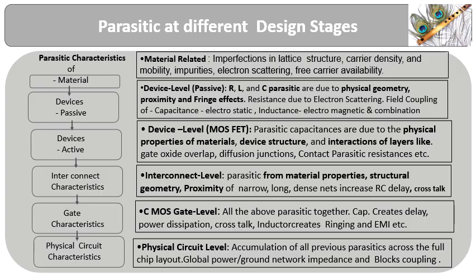At the gate level, these parasitics manifest as slower switching speeds and increased leakage currents, directly impacting power efficiency and speed. When observed at the functional level, they can cause timing failures, signal noise, and long-term reliability issues, threatening the overall integrity of the chip. Furthermore, second-order nanoscale phenomena, such as fringing fields, electromigration, and self-heating, introduce even more complex challenges as technology scales down. To address these issues, careful design practices, judicious material selection, and optimized layout strategies are essential for delivering high-performance, reliable modern VLSI circuits.